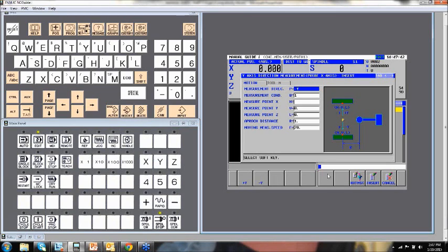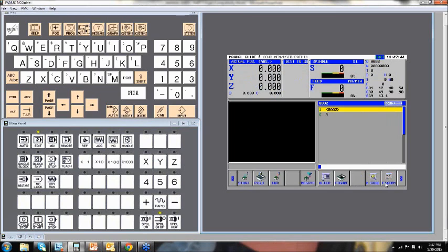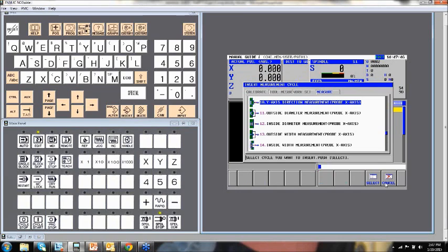So those are all the different cycles. And again, with these cycles that we just went over, these all can be inserted into any FANUC CNC that has Manual Guide i, even if you do the program itself offline. You can insert those into a standard G-code program that will read it, no problem.